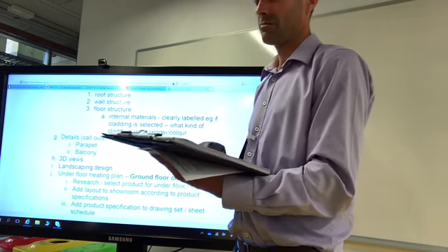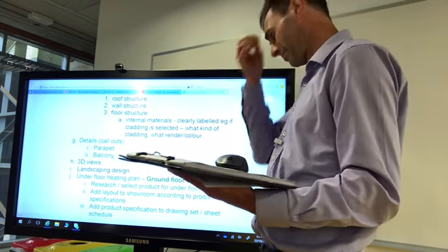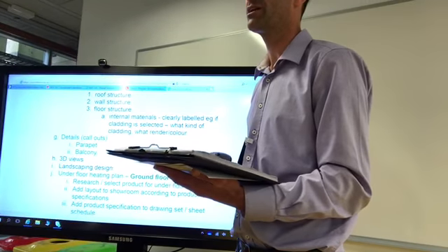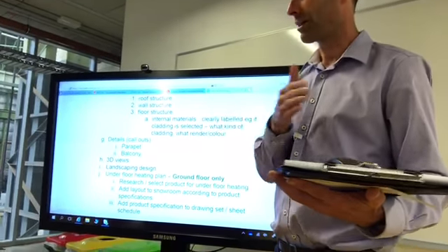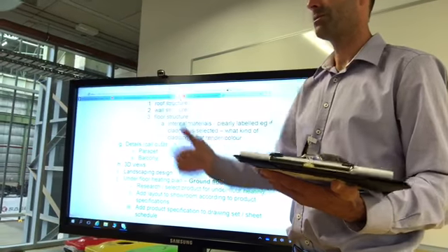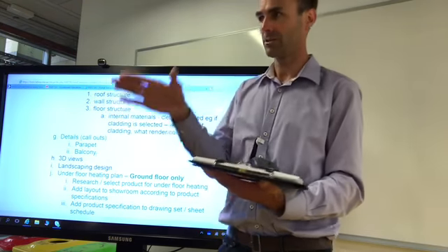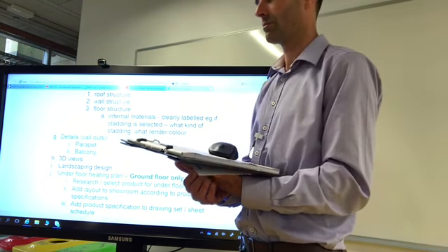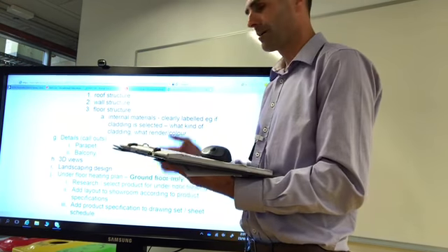But the method I suggest for this building, what I'd expect to see on site, is that it's actually a concrete floor formed up, and that concrete floor is carried out past the facade of the building, creating the balcony. So this is the balcony that's at the rear of the building, by the way. So we're not punching through our curtain wall glazing for a balcony. We're taking that out the back.